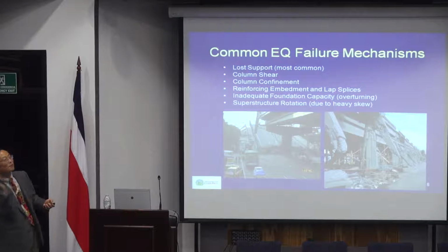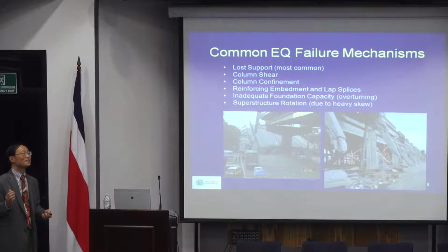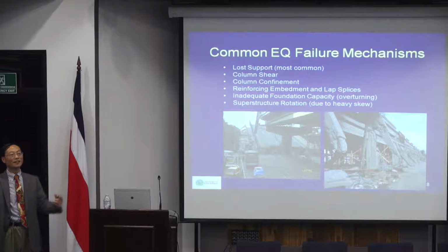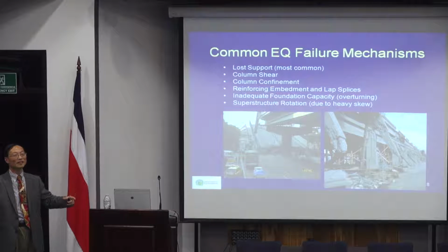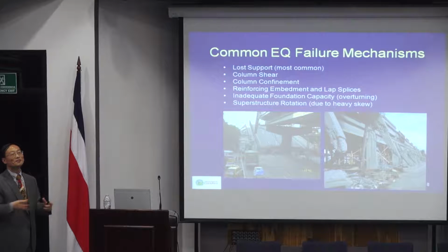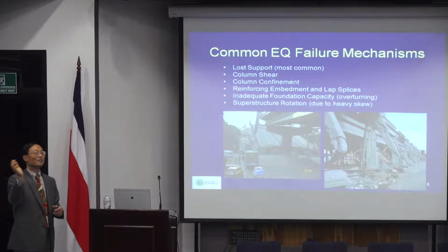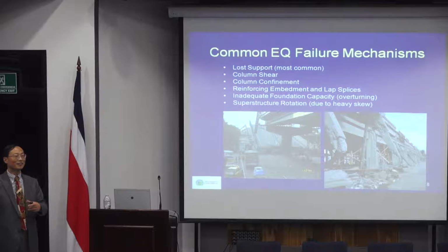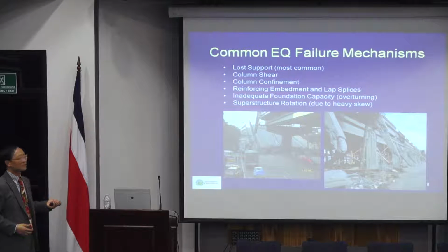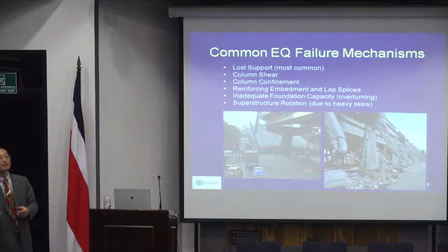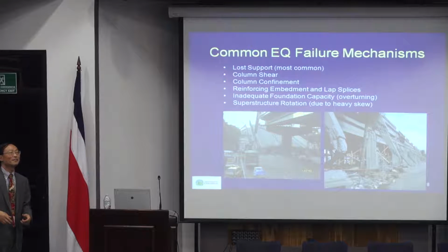Again, it's a similar situation. If you design a foundation, for piles or spread footing, only for vertical load, you don't need many piles. But if you have vertical load plus an earthquake lateral load, then you need a lot more piles. That's why if it was not designed for earthquake load, the foundation may fail. So these are the three basic failure modes. And of course, to address the problem, basically you only need to address these three problems.